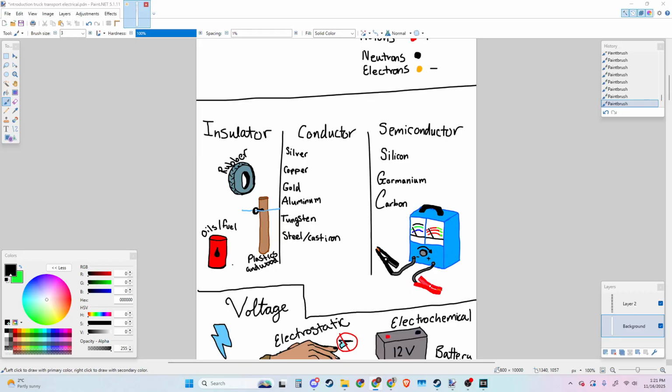And the reason why we don't use silver, although it's the best conductor we have, is that it corrodes rapidly. Copper has relatively low resistance. It's pretty cheap, pretty resistant to corrosion, and pretty flexible. Gold, on the other hand, has higher resistance than copper, but is often used to plate contacts. You'll see that usually in ECMs or motherboards or any sort of electrical components, computers. They always use gold for good contacts.